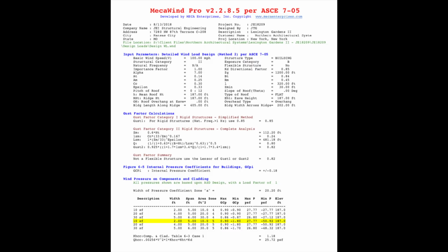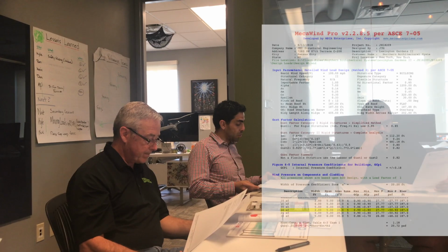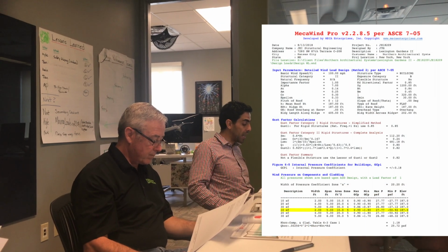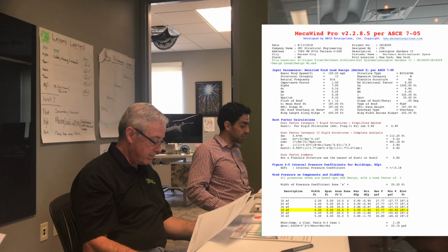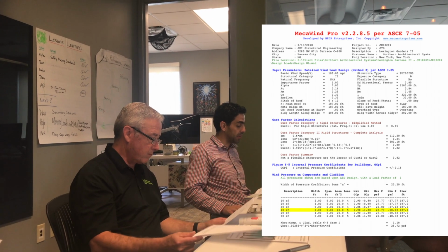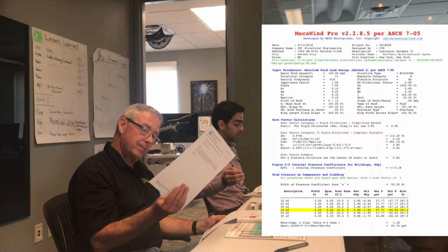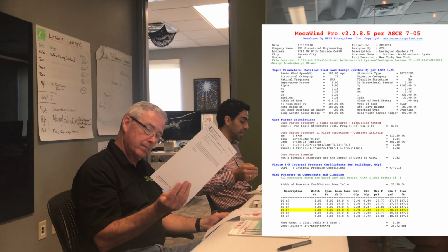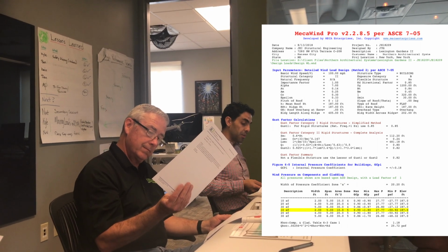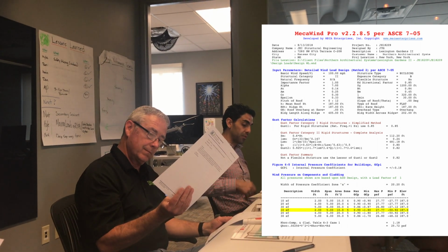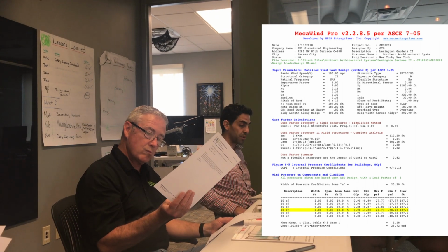So on the back of that page, you see the design pressures for a cornerstone frame. The cornerstone pressure is about twice as much as a non-cornerstone pressure. So you have a 27.7 psi for the positive pressure, and then 50.9 for the negative pressure. I included the RISA model of this one window frame that shows the maximum head reaction of 362 pounds. This reaction comes from the negative suction wind load pressure.